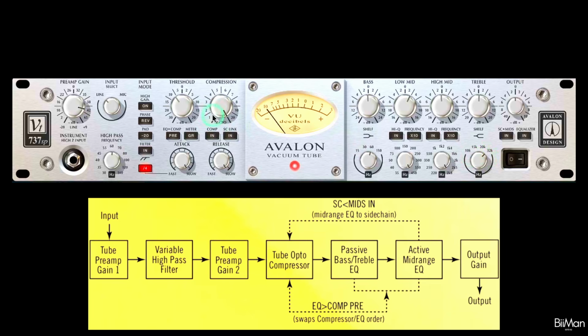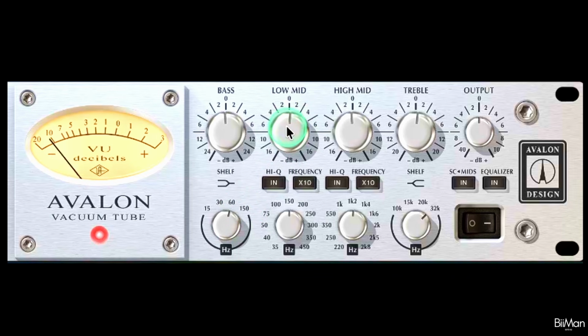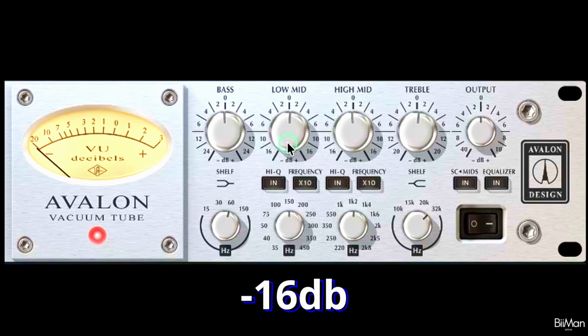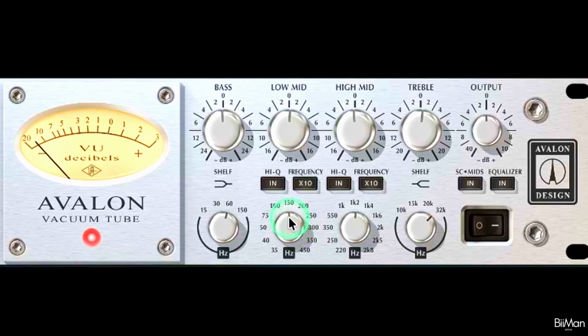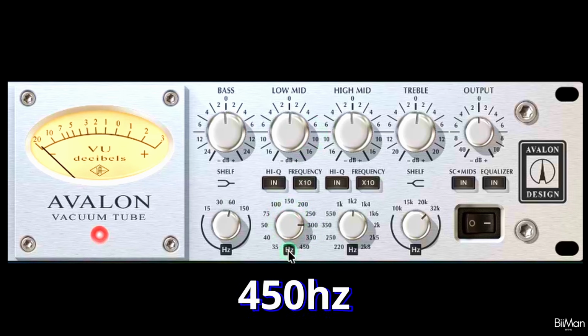Remember that the signal flow goes from the passive bass and treble EQ before it goes into the active mid-range EQ. This is followed by the low mid gain. This lets you boost and reduce the low mid-range band up to +16 dB and -16 dB. Right below that, you have the low mid frequency knob to select the different low mid frequencies from. This goes from 35 Hz to 450 Hz.